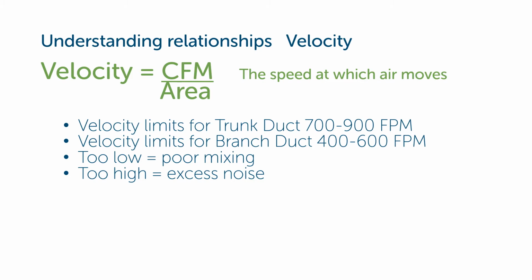If the velocity is too low, the air is not going to mix in the room. Like we're not going to get enough flow out of our registers to mix the air in a room, and we're going to have stratifying temperatures. If it's too high, we're going to make noise, and people hate to hear the noise from the air system. So if the velocity is too high, we're going to hear the air whooshing across the registers. That's going to make people unhappy. It's important to get the balance right and get the velocity right.